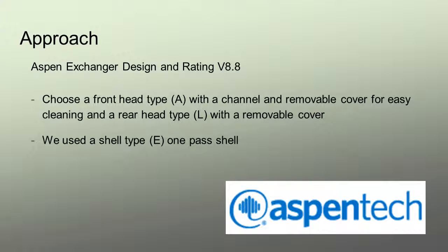The configuration of heat exchanger we chose to use is with the front head type A and a rear head type L. These both have removable covers which will allow for easy cleaning. We also chose to use a shell type E, which is a one-pass shell, so the water does not get too hot.